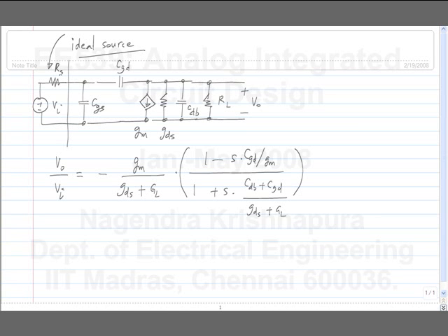First of all, CGS was out of the picture in the original circuit, so now it will come into the picture. It will become second order: 3 capacitors in a loop, 2 of them being independent. Okay, second order. And can you say something about the poles and zeros?